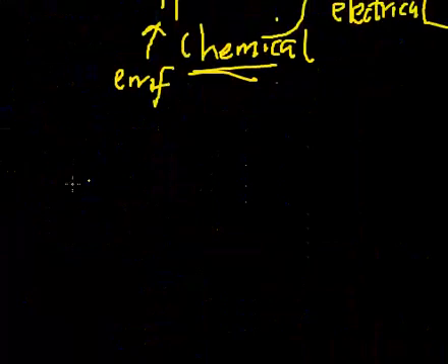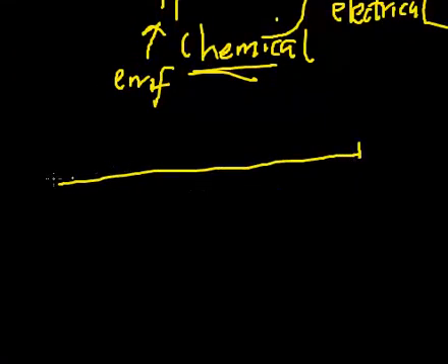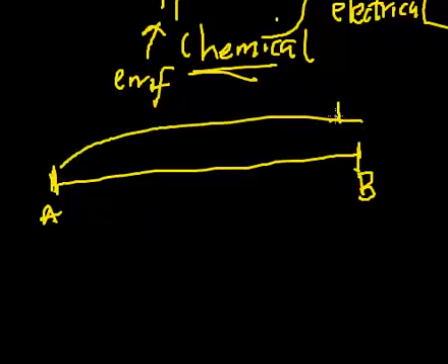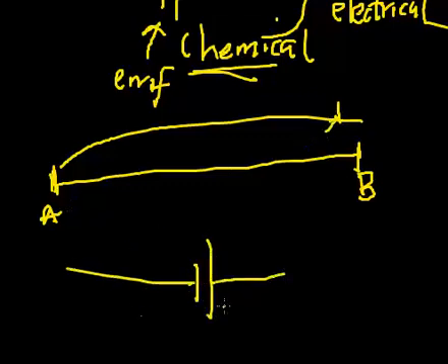So it simply means that if I have a conductor, let's say from this part A to part B, the potential difference between these two ends is actually the work done in moving a charge from this part to this part. All right, and what provides the energy for that work to be done is EMF. So have you seen the difference now? If you are asked to differentiate between EMF and potential difference, please take note of that. I hope that is well understood.